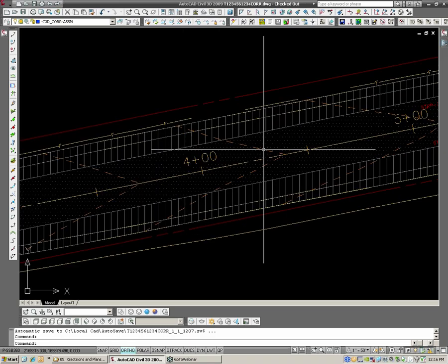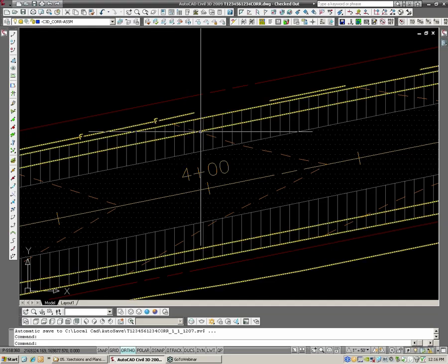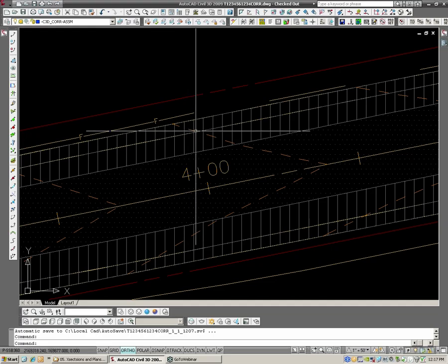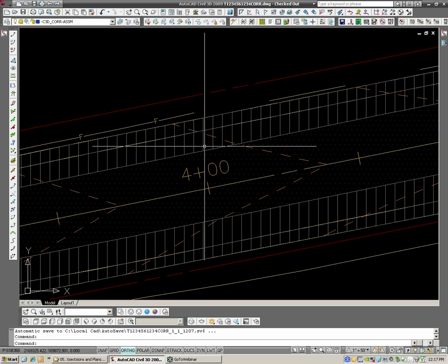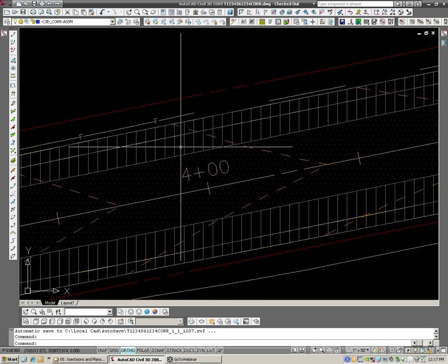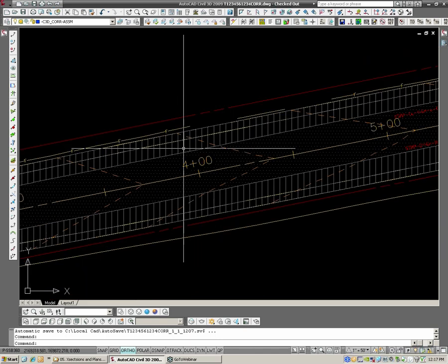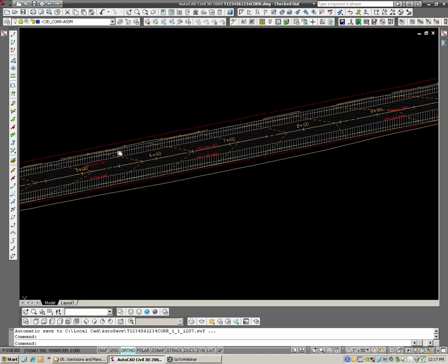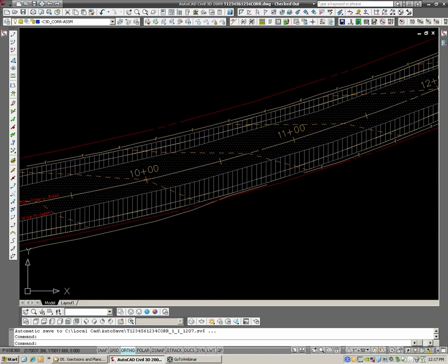all the way across. Notice there's no grade breaks. Typically, if this would be the top surface, it would have a grade break here where I go from edge of overlay to my shoulder, since this is at 5% or 6%, and my paved sections are at 2% cross slope. So you can see that reference there. That goes across and it shows the super.